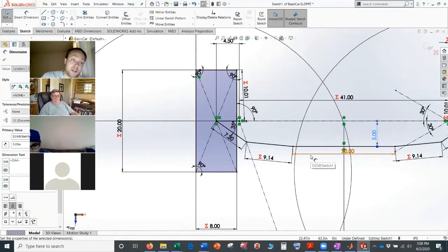I would design my steering column secondly to this. This would be more important to me than getting my steering column angles right. It needs to fit with the driver, right? I would care more about where this lands in the driver's feet. You don't want this up near your pedals, because you can change the angle of the steering column relatively easily compared to the other stuff. It's not as constrained.